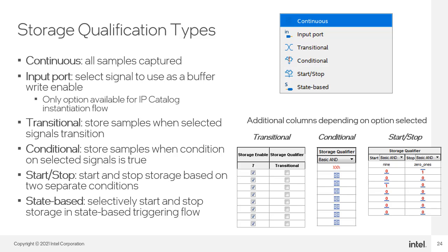The other storage qualifier settings let you select the input port for the input port qualification type, mark in the waveform viewer where data discontinuities occur due to storage qualification, and disable storage qualification on the fly during runtime. With this setting, you can instantly turn off qualification during analysis without having to recompile the logic analyzer. Changing the storage qualification type, however, will always require a recompile.